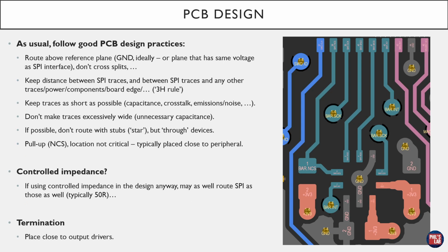In terms of PCB design, again, SPI is a very, very simple interface. There is not terribly much that can go wrong. We want to follow the usual PCB design best practices, so that is a route above a reference plane, ground ideally, or a plane that has the same voltage as the SPI interface, don't cross splits. Follow the usual good practices.